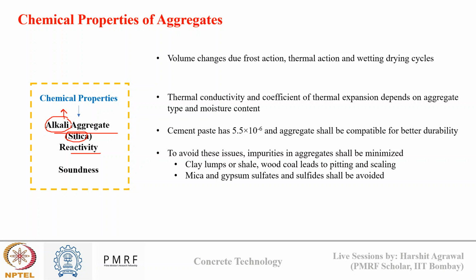However, if my aggregates are not inert, they have some reactive silica. That reactive silica reacts with alkali and they form a gel, which is expansive in nature, and that expansive gel causes cracking in aggregate. That is not desirable. So that's why we need to determine the chemical properties of aggregate also. More we will discuss in the durability class, not right now.